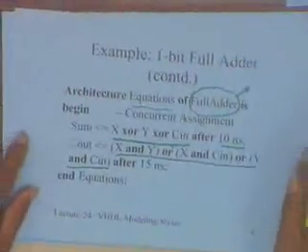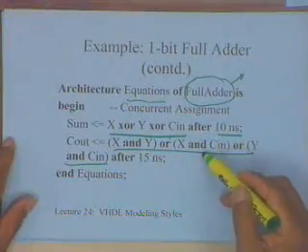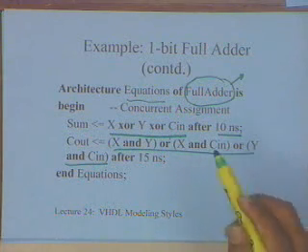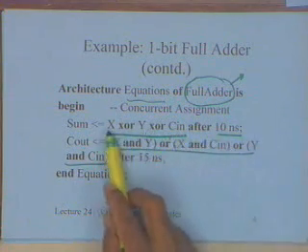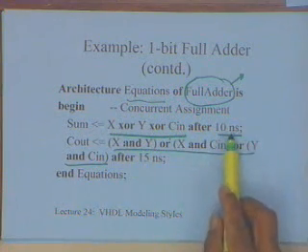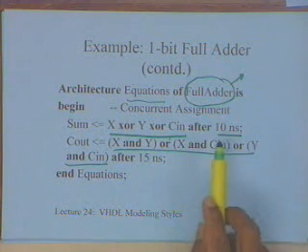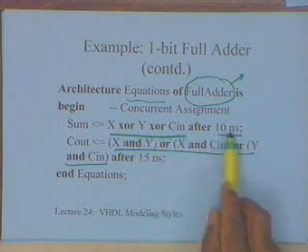So, that is the semantics of this statement. Here it really does not matter whether you write this earlier or this one earlier. What many people who learn VHDL for the first time get confused about is thinking that you are going to wait here for 10 nanoseconds. Please do not do that, that is not the semantics. There is no wait here.